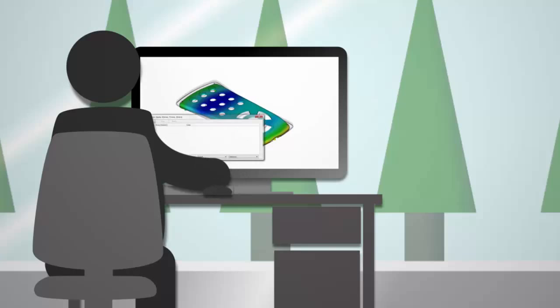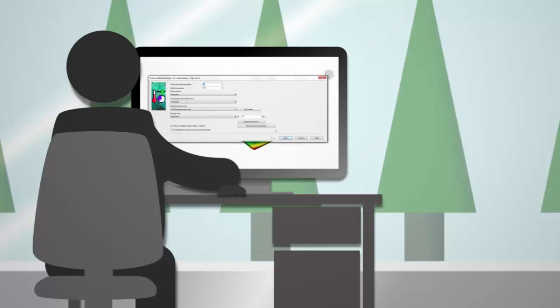The Examine Result tool is useful when paired with the deflection result. You can identify individual points and display their coordinates before and after shrinkage to see how far those points have moved. Then, you can alter the processing conditions or redesign the part or mold to change the shrinkage that you identified using this result.